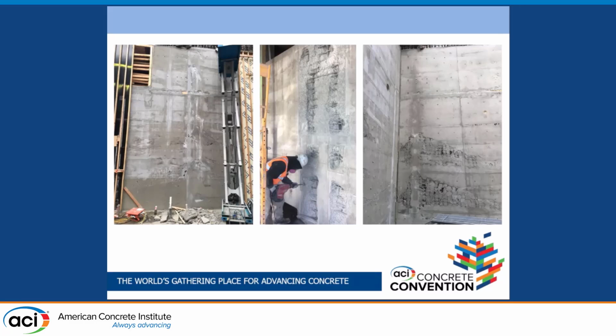The concrete is not going to have the access and the ability to encapsulate the rebar, and it's not going to be able to travel to the front of that formed surface and create a nice finish. Right? So what happens then? You start creating rework, right? Look at that guy. He's doing some rework there. And what happens when you expose people to rework?